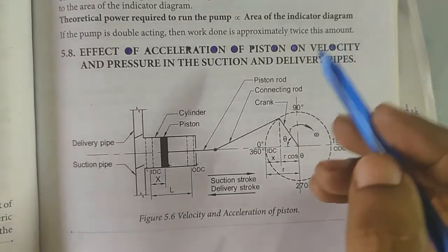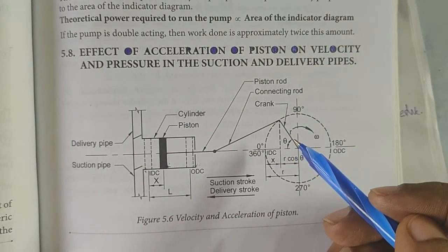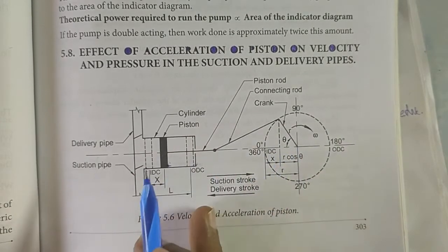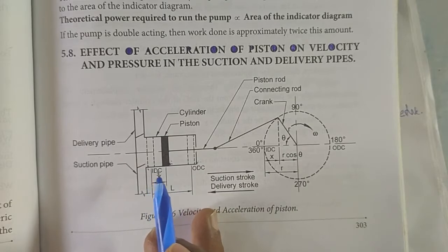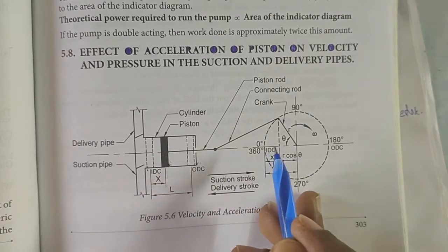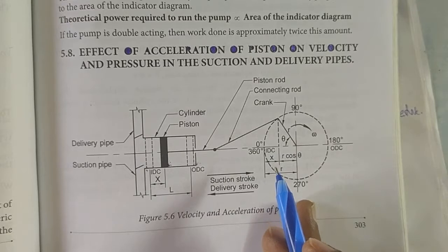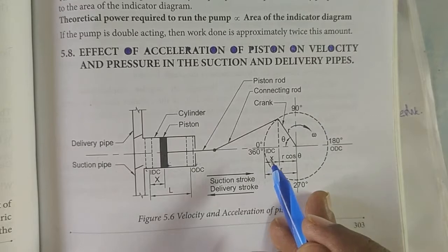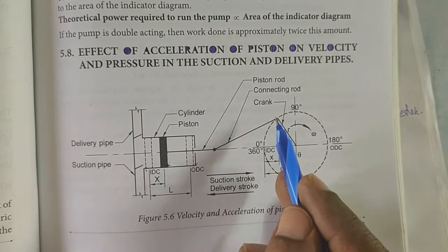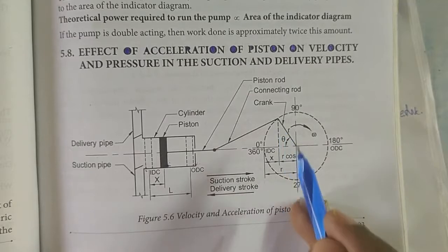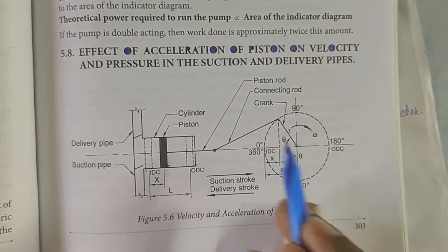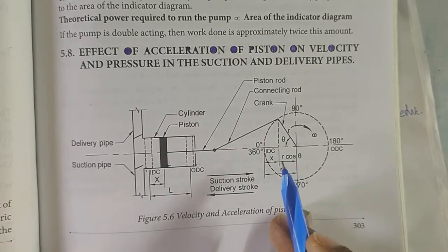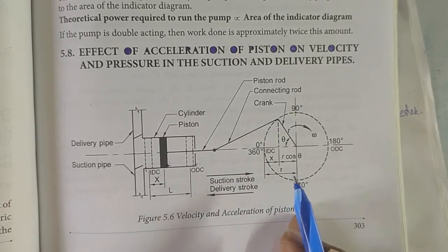Okay. So the crank is considered to be at a particular instant of theta. Then when the crank rotates through theta angle, the piston moves through a linear distance of x, that is shown here. Now what is actually x? X will be equal to, if this is r, the radius of the crank, this will be also r. So if this is r, if this is theta, this is r cos theta. So x will be equal to r minus r cos theta.